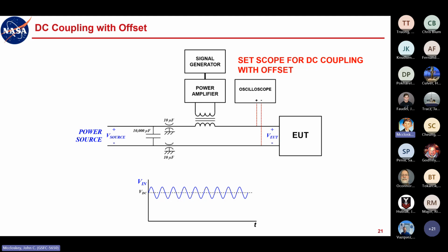If it's a fairly slow square wave, slow compared to the charge and discharge characteristics of your capacitor and whatever resistance it can charge and discharge through, you get a distorted version of the square wave, right? That distorted version, where you get the charge and discharge on the plateaus of the square wave, is not real. It's a manifestation of how you're making the measurement.